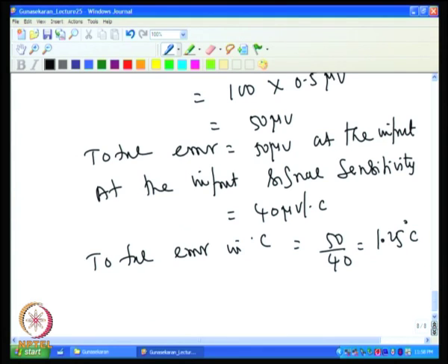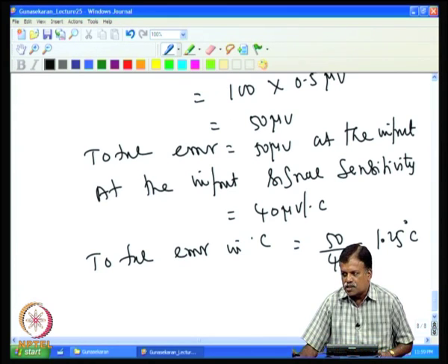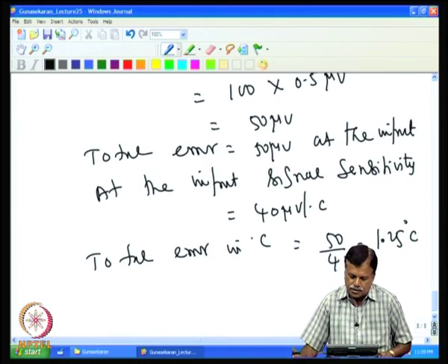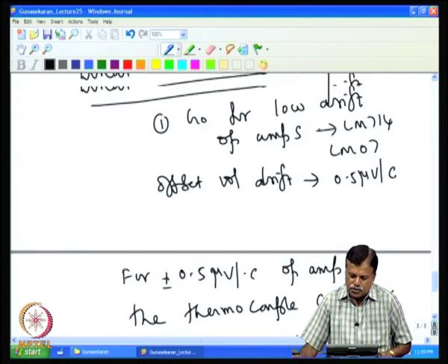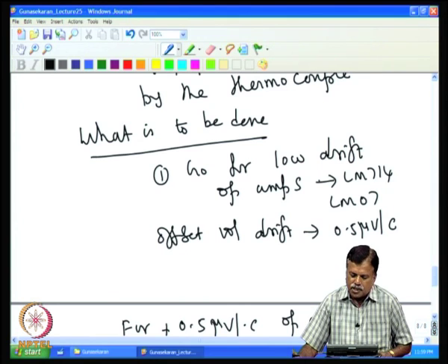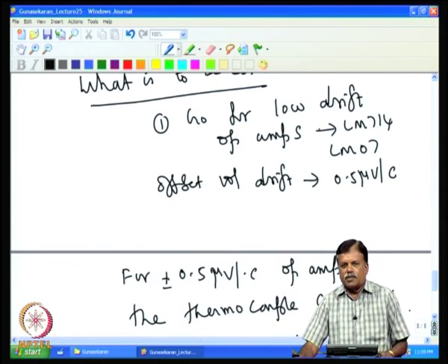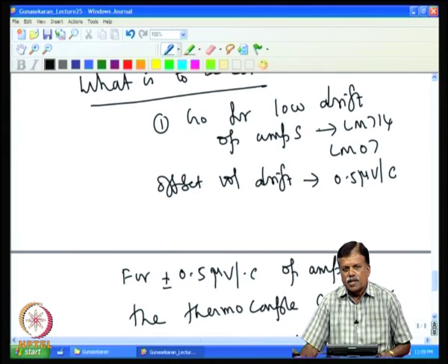So, that is why we have a class of amplifiers called low drift operational amplifiers, and this is a very important thing one has to consider when designing a DC circuit, because one has to see what is the actual drift that is coming because of offset voltage drift, and this can be reduced only by going for the low drift op amp. When you are making hundreds of units, each op amp that you are using will have a different amount of drift.